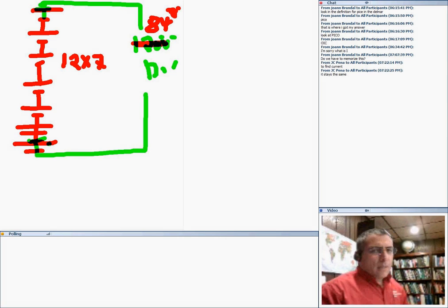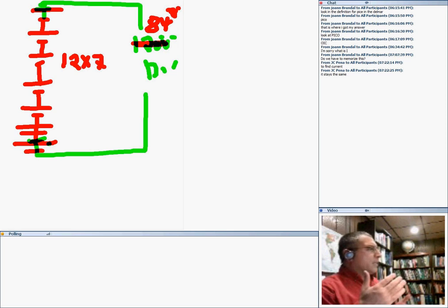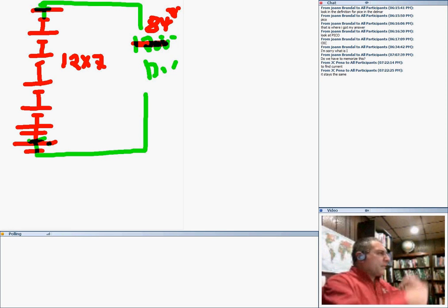In data centers. If you have seen data centers, they want to build a battery backup system so they can back up the whole building, but they can't back it up with 12 volts or 24 volts. They need to build the voltage up to 660 or so. So they start putting these batteries in series, positive to negative, positive to negative.